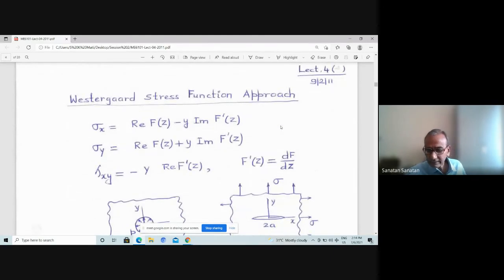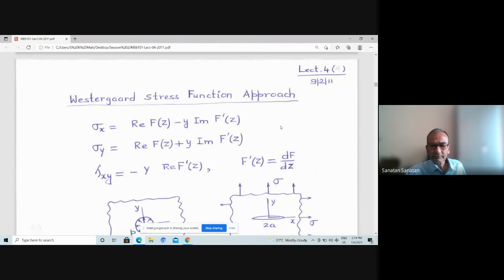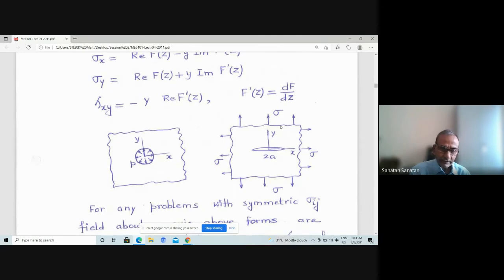So this is the basis: the stress function approach of Kolosov-Muskhelishvili or the Airy stress function is the basis of finding the solution for stress distribution in the elastic body, and it gets facilitated by this Kolosov-Muskhelishvili potential formulation if you have crack problems. And some more refinement was done. When there is, let's say, a plate with a circular hole and it is subjected to internal pressure, it is called a bearing problem. If you have a plate with a circular cutout and loading on its boundary in the radial direction, it is a double symmetric problem. The stress distribution is symmetric about the x-axis and y-axis.